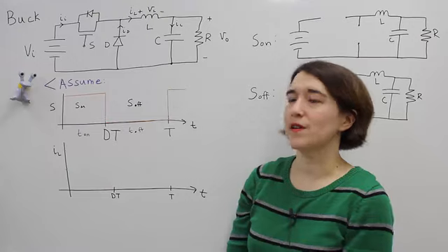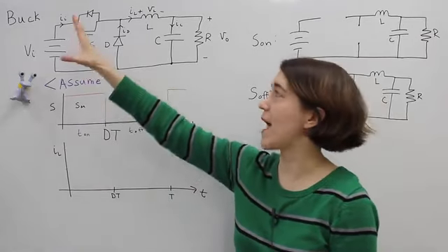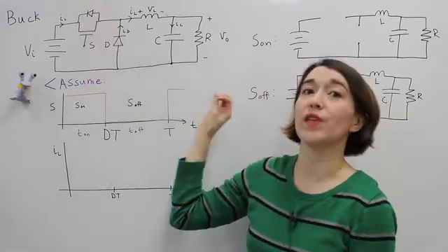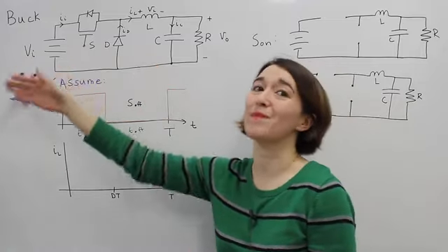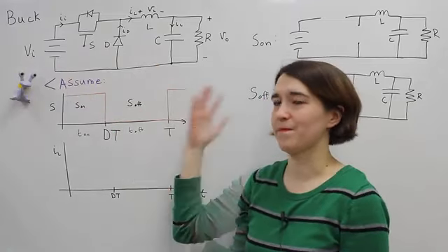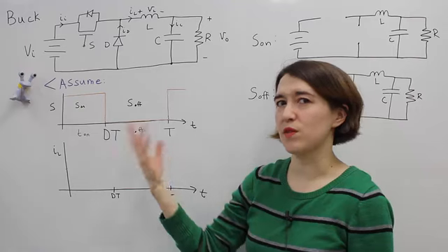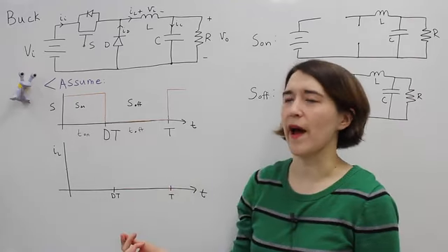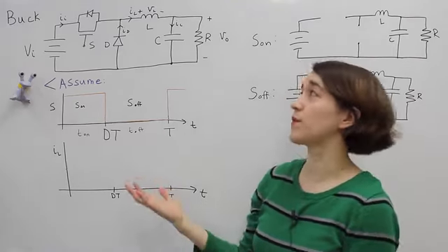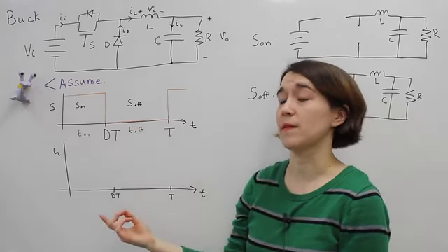So the buck converter takes a higher voltage and the output will be lower than that voltage. So we're bucking, or stepping down, the voltage. We just said it switches between two states. Let's look closer at how the circuit is represented during those two different states.